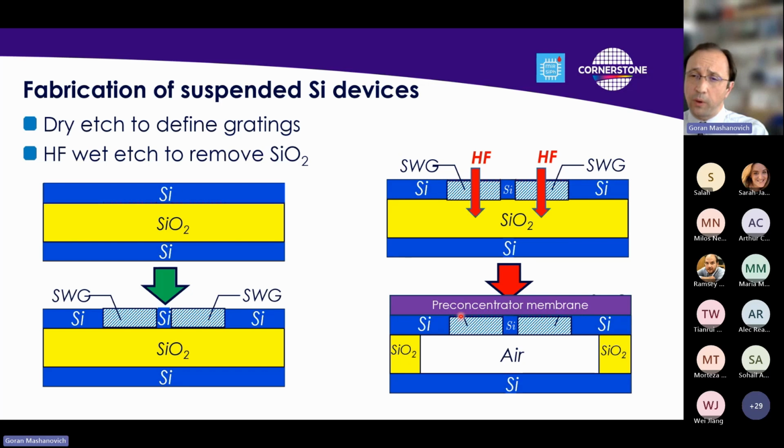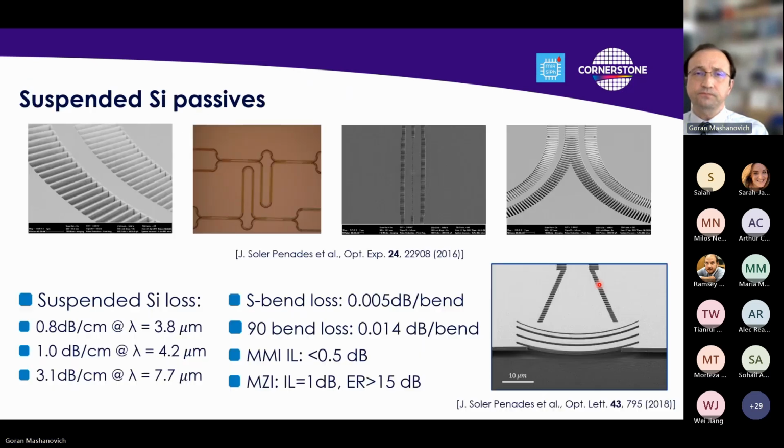Then we can cover our waveguide with a certain polymer. That polymer can contain so-called cage molecules, which will attract, let's say, methane. And it can also repel water, because water absorbs a lot in the mid-infrared. So we can get these methane molecules close to the waveguide, but no water there. And that's how we can reduce limit of detection, get better performance of our sensors.